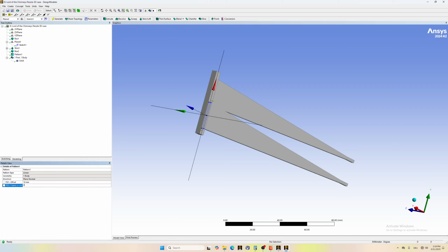But let's say we want 3 nozzles. So we put there 3, generate, and we have, so 2 plus 3 plus 1. So this will generate 3. So you see automatically also the outlet part is generated, which is a really great thing, and these are the nozzles. So we have inlet 1, inlet 2, inlet 3, and the one big outlet or pressure outlet.